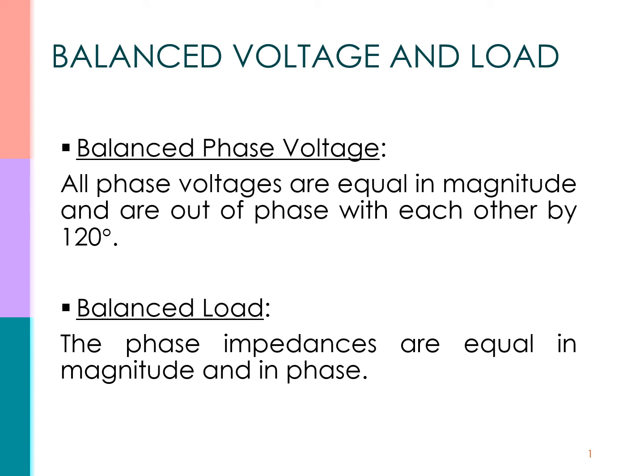As we discussed about balanced three-phase circuits, of course the voltage and load are balanced in terms of magnitude and out of phase with each other by 120 degrees. So we have the term balanced phase voltage, where all phase voltages are equal in magnitude and out of phase with each other by 120, and the voltage is connected to a balanced load where the phase impedances are equal in magnitude and in phase.